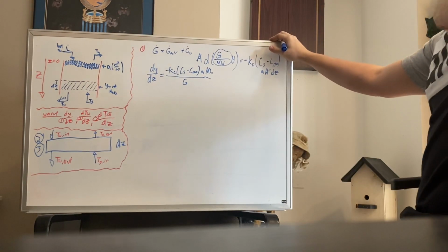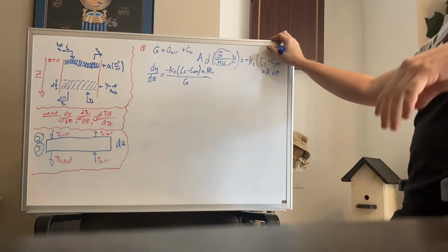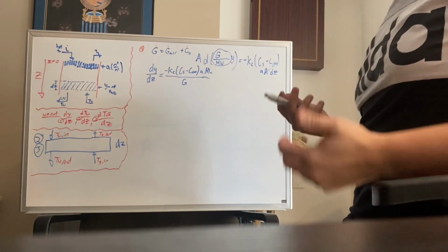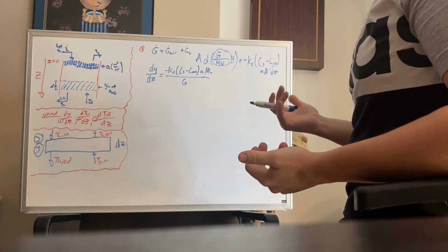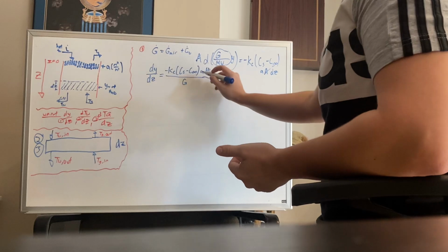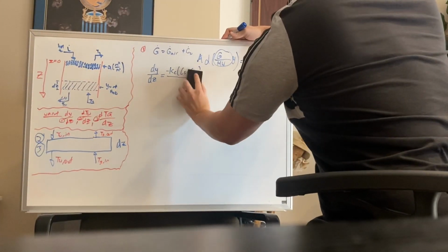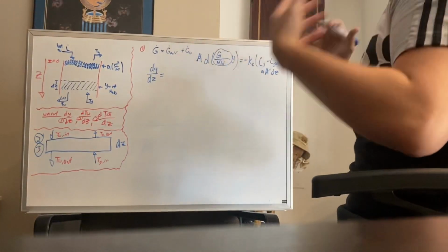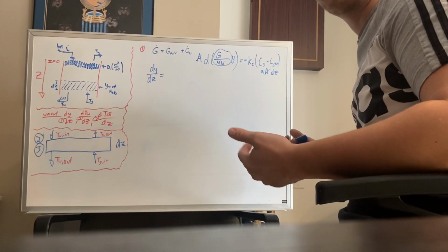So I'm pretty sure that looks correct for the time being, but we can modify this even more, and that's what I was looking at trying to do. We can go ahead and modify these concentrations to represent the partial pressures instead, and make it look at the aspect of being an ideal gas. So we would end up taking out the negative mass transfer coefficient and the specific area. And here, I'll just go ahead and erase this, because I'm going to be needing the space to go through the other two differentials in a second. So what we will do is transfer that molecular weight over the gas flow rate multiplied by these concentrations, and that's going to give us the partial pressure of an ideal gas.